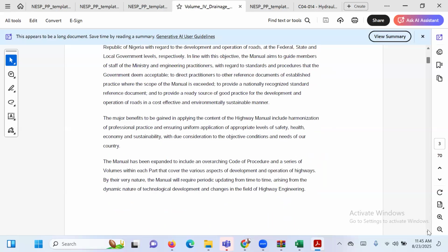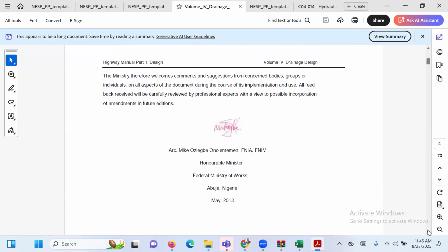And for the place I designed, the client told the consultant engineer I'm working with that I should use a runoff coefficient of 0.9. I told him that area is a local area, we're going to use 0.7. So we used a runoff coefficient of 0.7 for our design. Why? Because we expect that 30% will infiltrate. We expect that only 70% will contribute to runoff, because it's a very virgin, growing area.